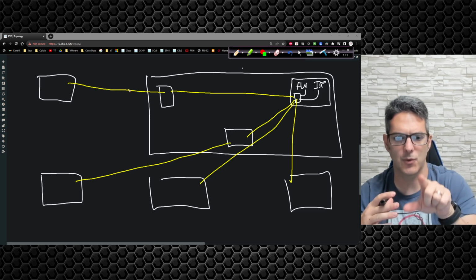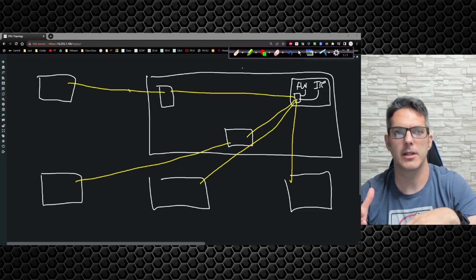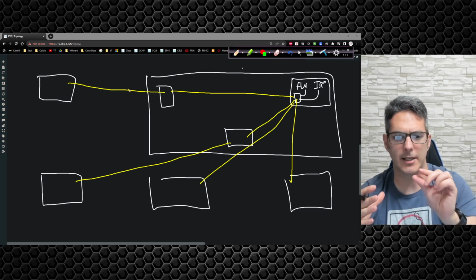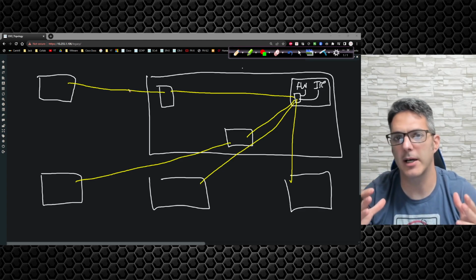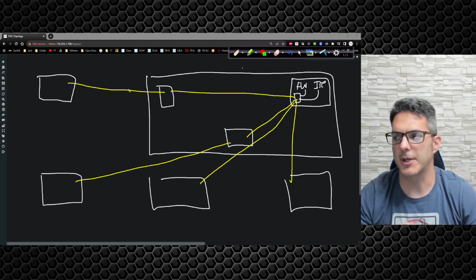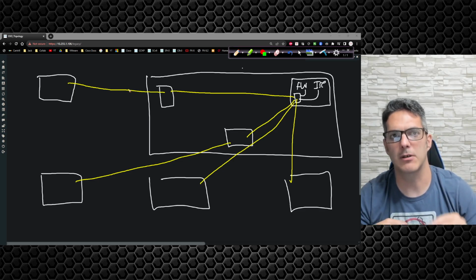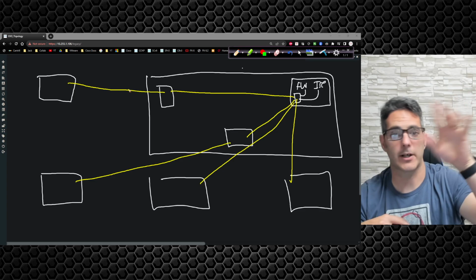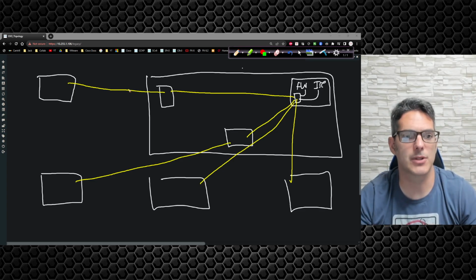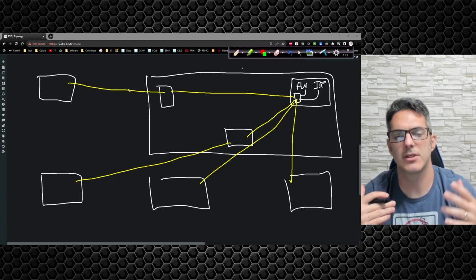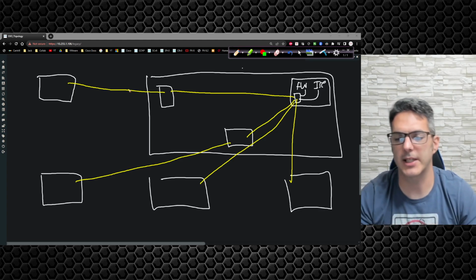So not the individual copper wires, but there's going to be foil wrapped around it to help deal with EMI, electromagnetic interference, because there is a potential that you could be laying copper over a fluorescent light or some other type of power source that could affect the copper cabling, things like that.